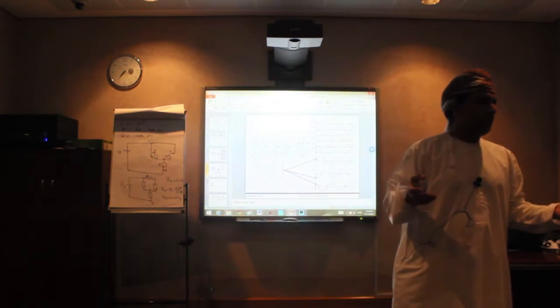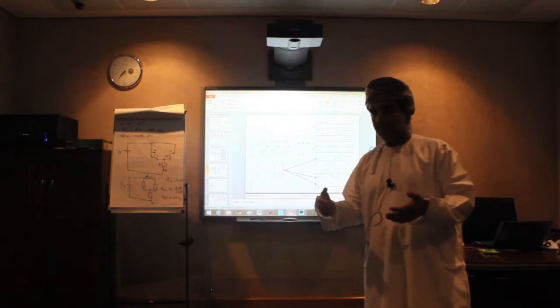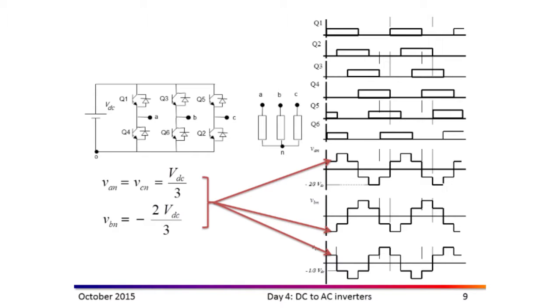And you know that, for example, with an induction motor, if you would like to change the speed, one of the techniques to control the speed is to change the frequency, right? If you can remember the relation for the induction machine, N equals 120 F over P. This is the synchronous speed, and the rotor speed should be slightly lower than it, right? In order to operate an induction motor in the stable region of its characteristic. So that means if I change the frequency, I can get different speeds, right? So I can speed up the motor, or I can decrease the speed.